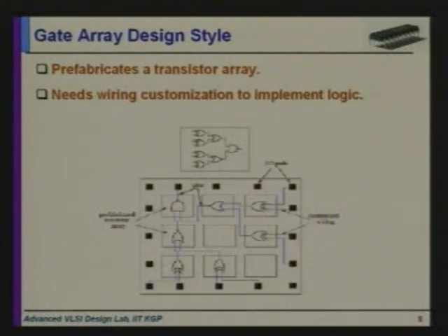And then we have the gate array style design. In the standard cell design, the cells were standard, but within the cells any type of layout can be generated. Here, in the gate array style design, we have a board which is composed of an array of gates only and nothing else, and we group gates to generate these standard cells. So we don't even generate the layout of those standard cells, that is also standardized here, right?